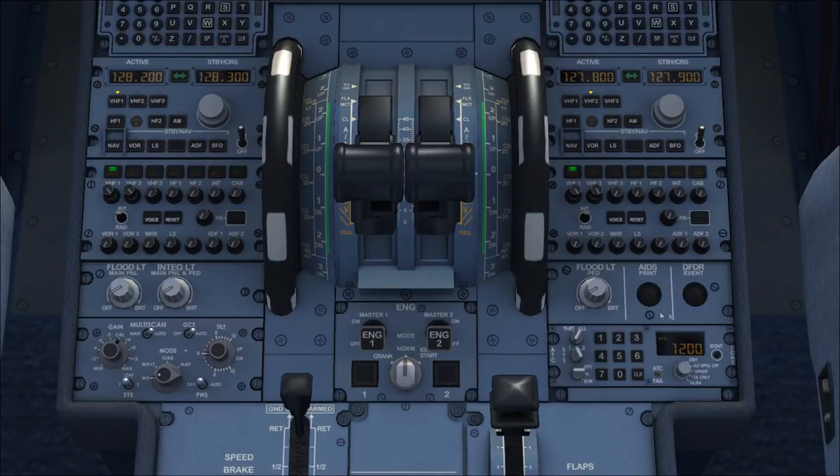And then on the right hand side, you've got two buttons here. You've got the aids print, which I believe is related to takeoff performance. You can actually print out a page of information which gives you takeoff performance for the plane, so you can do that if you wish. And you also have a flight recorder event there, so if something happens during the flight and you want it to be kind of noted or bookmarked on the recording of this flight, then you can hit that button there, and that will sort of bookmark a particular time during the flight, so you can go back and review what happened there.